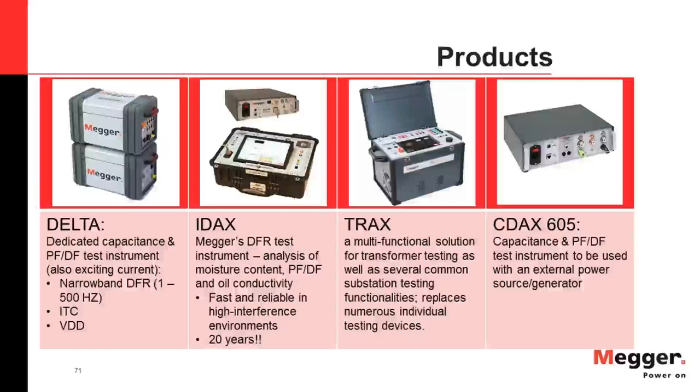You don't know what you're energizing, especially if it's an investigation of a potentially failed unit. So there's so many reasons why that screams safety hazard. I have to be really sure that power factor and dissipation factor and capacitance had enough diagnostic prowess that it would make it worth my time to do it. And I'm not so sure that I'd be convinced of that.